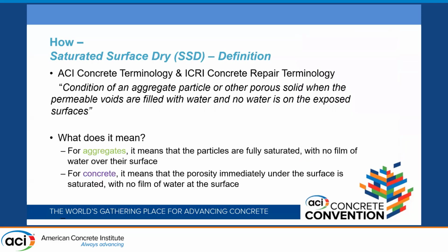Let's look at SSD condition. ACI and ICRI have the same terminology for SSD. It refers to the condition of an aggregate particle or other porous source when the permeable voids are filled with water and there's no water on the exposed surface. So what does that mean? For aggregates, it means that the particle is fully saturated with no film of water over the surface. For concrete, it means the porosity immediately under the surface is saturated with no film of water at the surface.